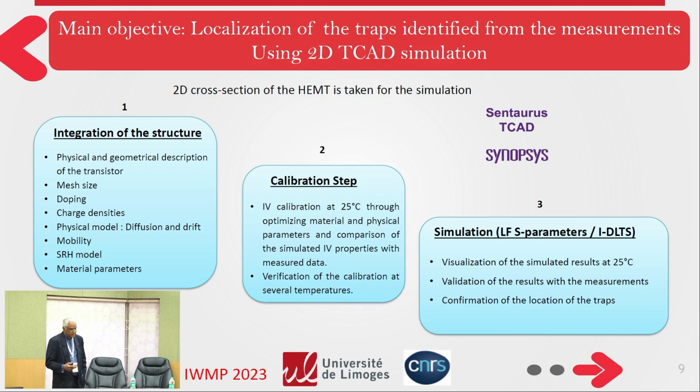That means you have to adjust the parameters of the TCAD model and essential parameters in order to compare the IV simulation result with measured data.